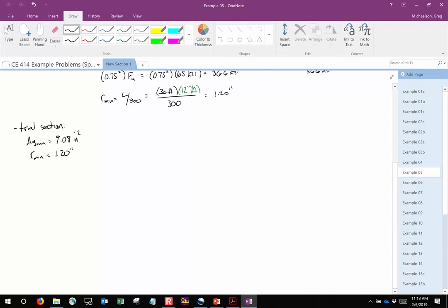Now, before we look anything up, this is a W shape. So when we look at the r's, should we be looking at rx or ry? ry. Remember, for W shapes, the minimum is always ry. So here's what I want you to do. We're looking up a W12. Let's open the manual, and let's find the lightest W12 that meets both these limits.